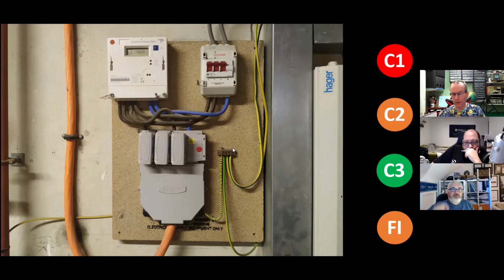But I think one of the lessons learned here, John, is, in recent times, I've gone into three-phase installations, looked at the head and assumed it was three-phase, and then looked closer and gone, hang on a minute, what they've done is they've swapped the cables out of the meter into different terminals on the top of the fuses and doubled up on some of the fuses because they had a network problem.